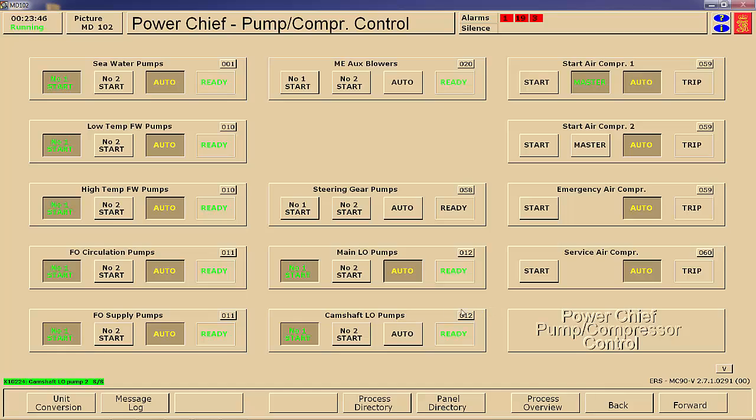Now, just so you know, and this is the reason I let this come up, for right now, for whatever reason in this version, it's tending to start this second pump when you first switch over. Just wait until the end of the exercise before you end the exercise and put it in automatic and watch, but I don't think the pump will start up if you just let it sit for a little while. So, watch for that. You don't want to, as you walk away, see two pumps running.